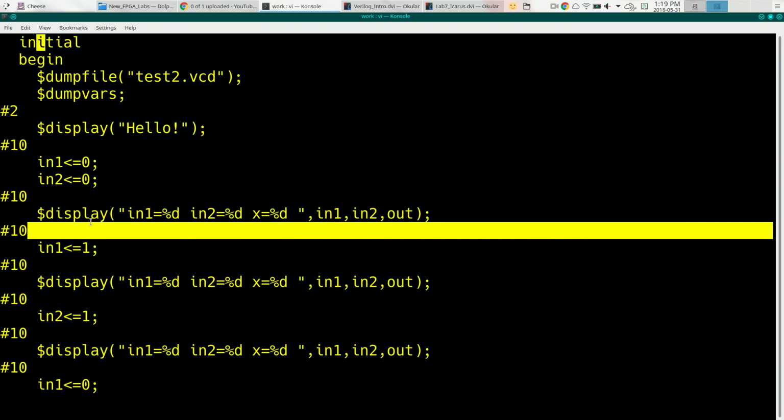You had a hand up. Do you have to put wait time? You don't have to, but if you're changing an input and you want to look at the outputs as a result, throw some wait time in, because these things do take time. I threw a lot of wait time in here just because I wanted to sort of do one thing per step, just for the sake of example.